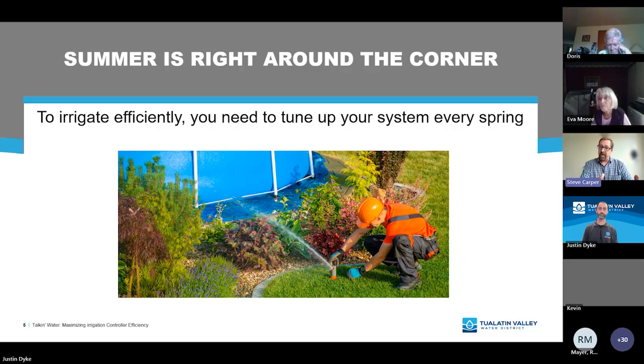And then you can compare that. Go back to your meter, set your timer for a minute, and let it go around. Now the meter is going to record water flow in cubic feet. You'd need to do a conversion, but basically you can do a comparison there. So if, based on the type of sprinklers in that zone, it should have 4 gallons per minute, and it's clear that you're using a lot more than that, then that's another indicator that something's going on subsurface that may not be surfacing and giving you a visual confirmation. But that's kind of a deep dive.